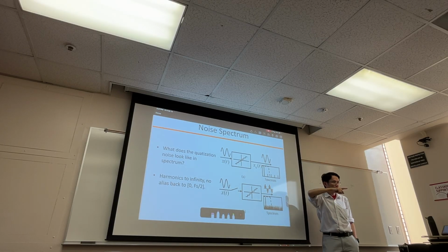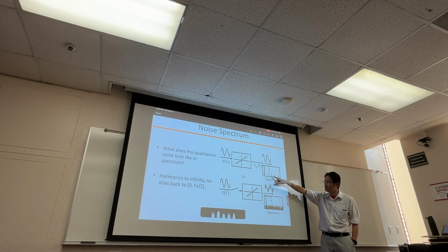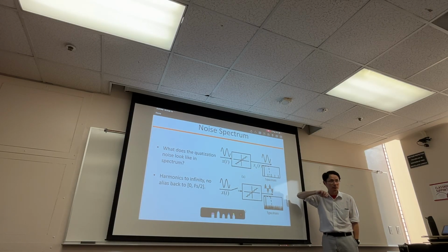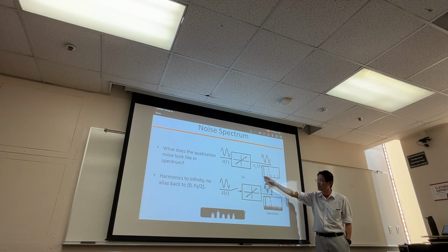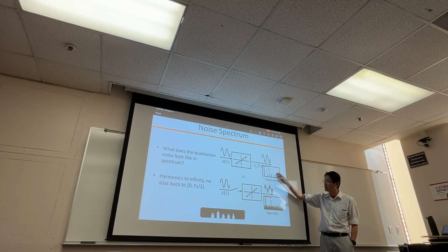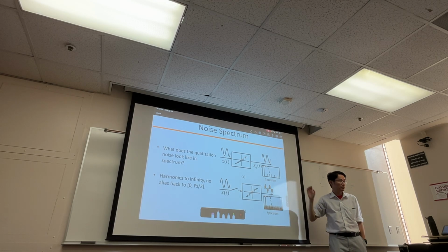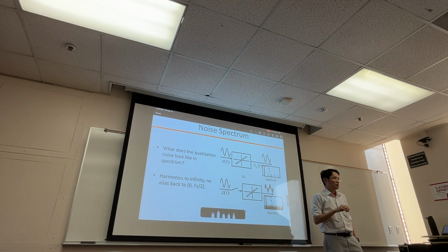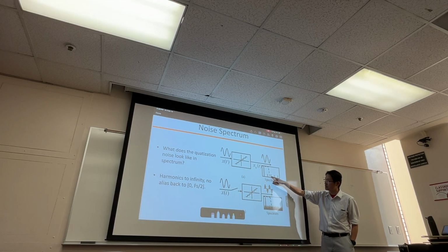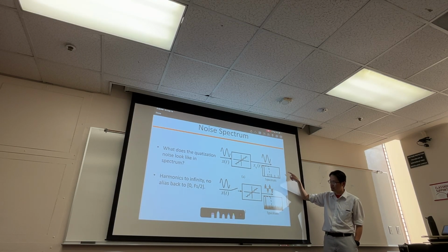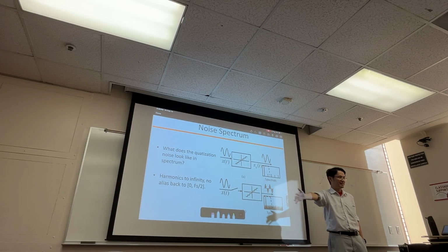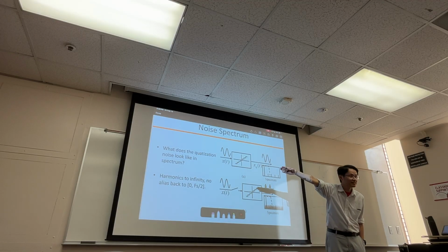All right, do you see the quantization errors? You do. You see these tones? These are what we call the harmonic tones. You have a sine wave, and harmonic means that it's an integer multiple of this. Those are the quantization errors. When does that end? This is the second harmonic, third harmonic, fourth harmonic, fifth harmonic. When does that end? It never ends. It just goes to infinity.